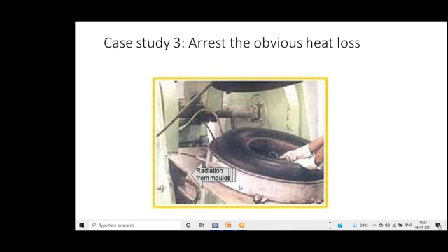So here what we did was again identify the root cause. Where is the heat coming from? The heat actually should go to the tube inside the mold. But why is it coming out? Then you attack the root cause. The root cause is that it is coming from the molds. Whatever thermic fluid is going, some portion is going to the tire tube and some portion is coming out as heat loss. Now, can we insulate this mold? Conventionally, nobody has done it. It's an unconventional way of thinking. There is a root cause we identified. What is the solution? We have to stop this heat loss.